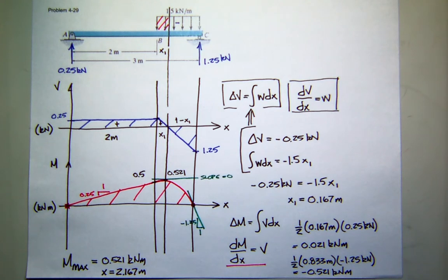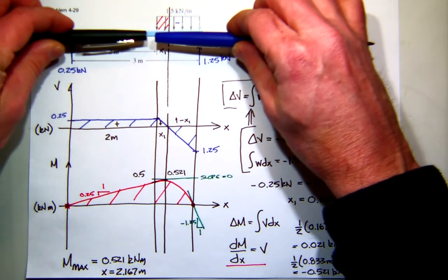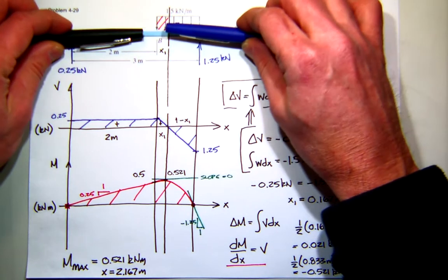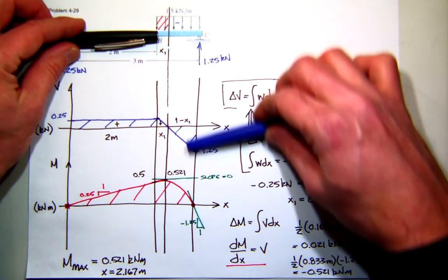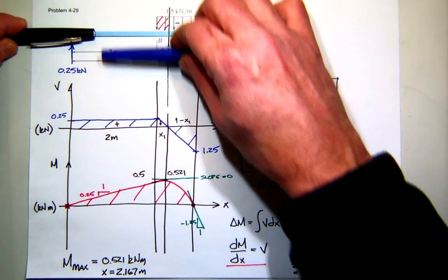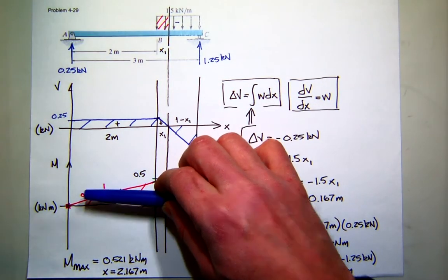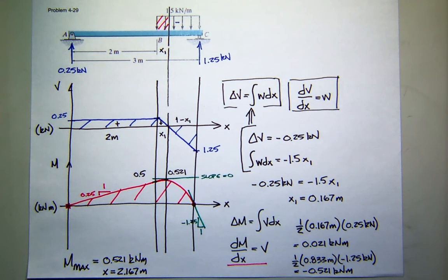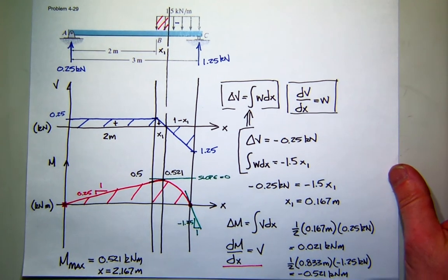So did we just find the max just to know? Well, you want to know the maximum moment because that's going to drive your design of the beam from that point on. And it's also important to know where it happens. If you were to design this beam, and let's say, for example, this beam just happens to be pieced together here by 2 pieces and you want to put a connection here, you're going to tell yourself, well, that's not a very good place because the moment's very high there. If you want to put a connection over here somewhere, that's a better place. The moment's much lower. So it'll give you some characteristics of the structure under the load and tell you how you might want to handle the design.